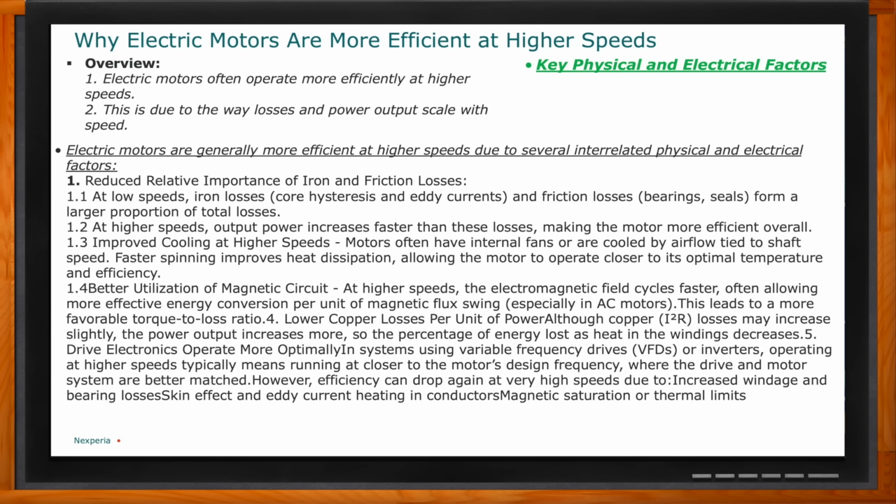The way we drive the motor, specifically the variable frequency drives that are being utilized now, even in the US, because we kind of run behind Asia and Europe, also will match motor frequency at the higher speed. The motors are designed to operate at a certain speed envelope, let's say between 100 RPM and 200 RPM. At the lower speed, they get less efficient. At the higher speed, they also get less efficient, but right there in between, the motors can have the same efficiency across the whole speed range, especially AC motors.